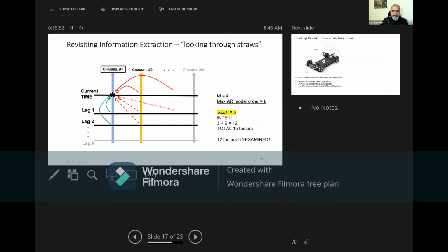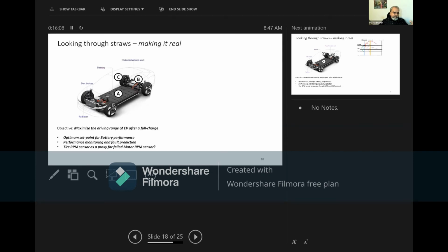Just a simple example, in the case of, let's say there are 4 bearings, like I said, today we are monitoring only 3 things. And in fact, 12 of these red arrows are ignored. Clearly, it'll have consequences. And the consequence is big, and some of my papers will describe it: it actually makes the green arrow estimation wrong many times. So not only do you not get the red arrow information, if you ignore it, and if that is significant, the green arrow data, those causalities, would be incorrect also.